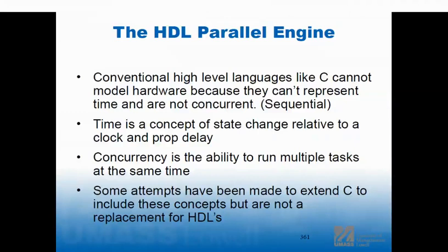So now they all become, I'll use the word, concurrent with that clock, but the simulator has a much easier time sorting that out because it's sorting out based on one event, not a bunch of timers that you spread out in the design. So there are other tricks for specific cases, but just think of it that way. The fewer triggers you have, the more efficiently a sequential oriented simulator is going to simulate your concurrent code, your concurrent design code.